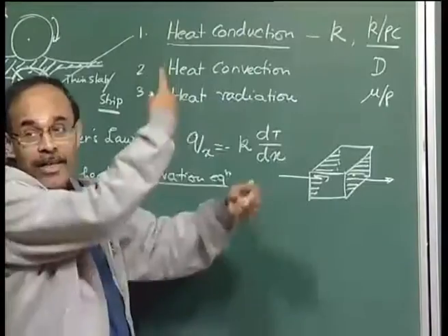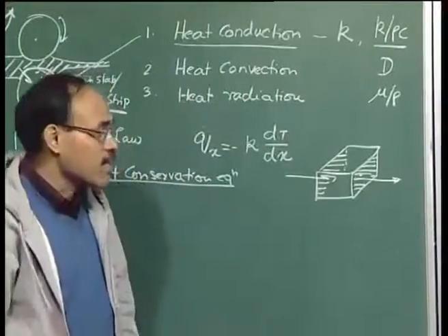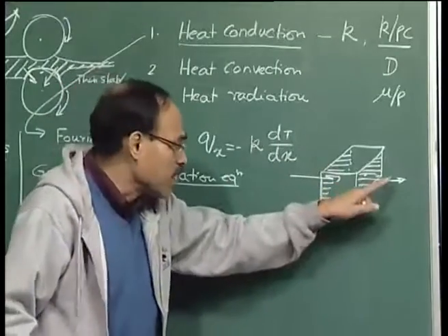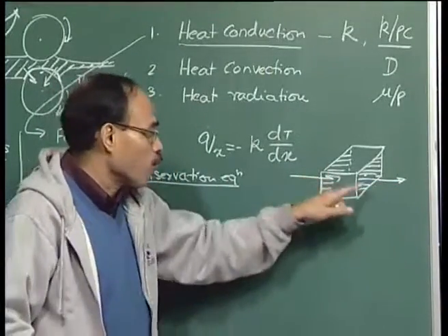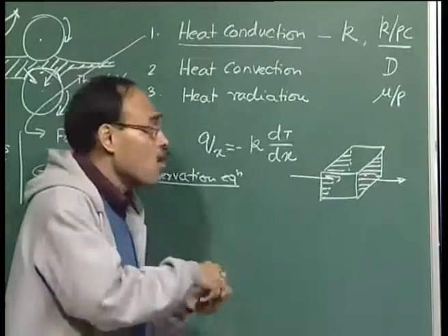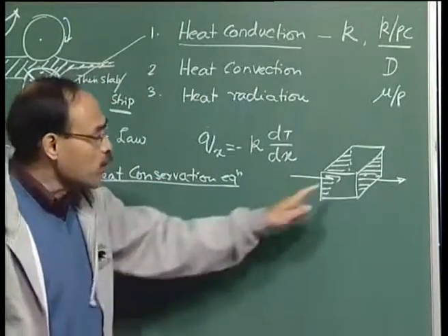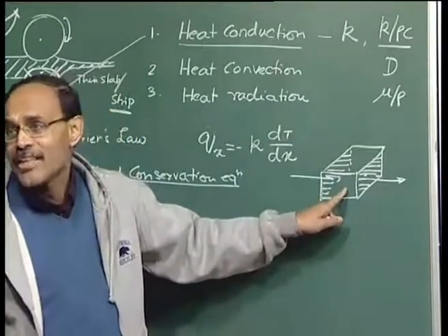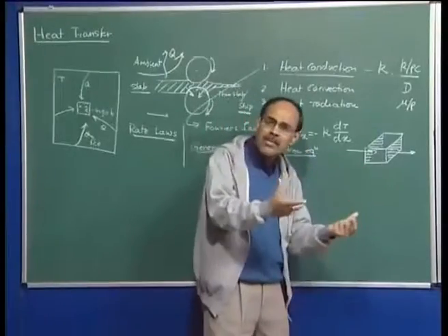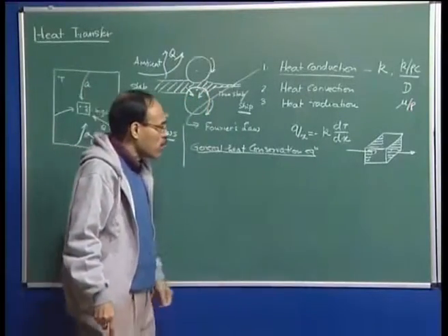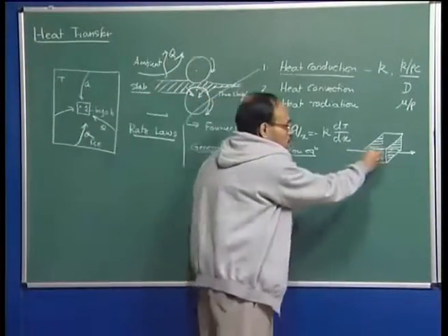If we do it in 3 different directions, how much heat is coming in, and the net difference between heat flowing in and heat flowing out will determine whether the temperature has increased or decreased. Also within the control volume, we may have a thermal source because of maybe a phase transformation reaction, or maybe a mechanical working process. So there may be some heat generation also.